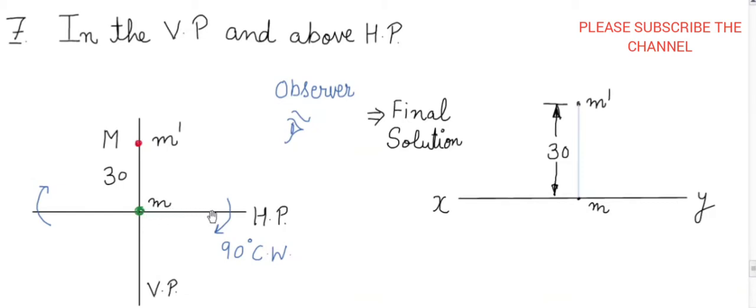So what will be the final solution? Rotating the HP 90-degree clockwise will result in overlapping of HP and VP, but this will not disturb our final projection. So the final projection will be: draw a reference line XY and mark a point small m, which is the top view, on this particular line, and 30 mm above that draw m dash, the front view of this point. So the rotating of HP doesn't affect our final projection in this case and in the upcoming case also. So do the necessary dimensioning, 30 mm also. So this was the final solution of this case. This was also a very easy case.